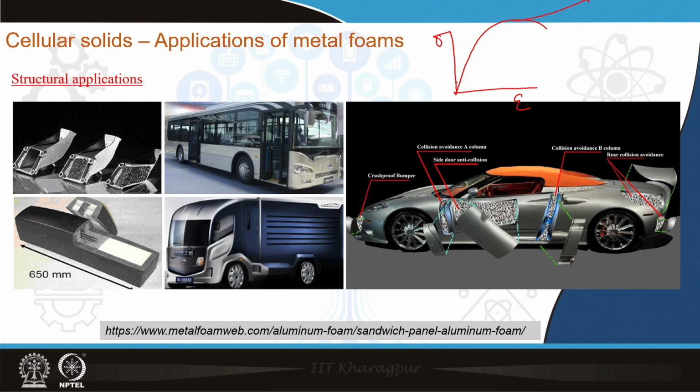But metal foams, as you will see afterward when we learn a bit more about metal foam micromechanics, show a different stress strain behavior when compressed. First of all they will have a lower Young's modulus, and then they will show a very long plateau, which can reach even 70-80% deformation.